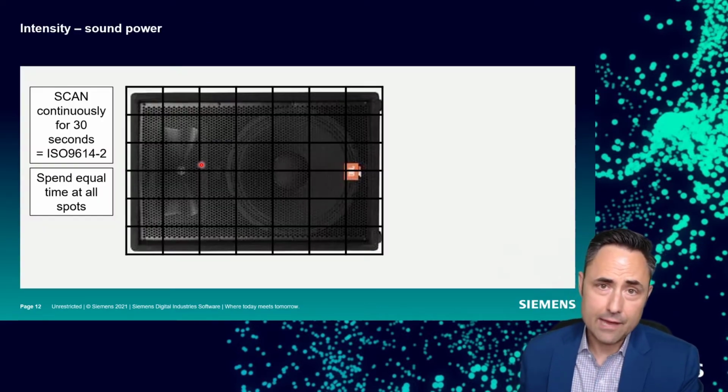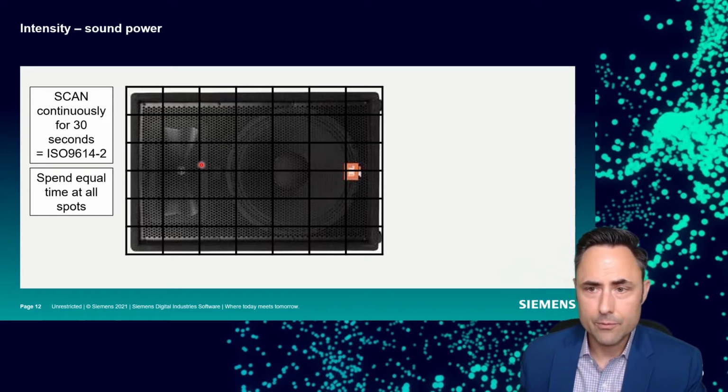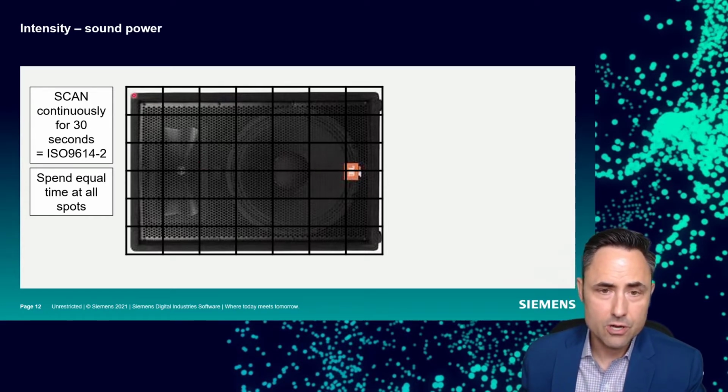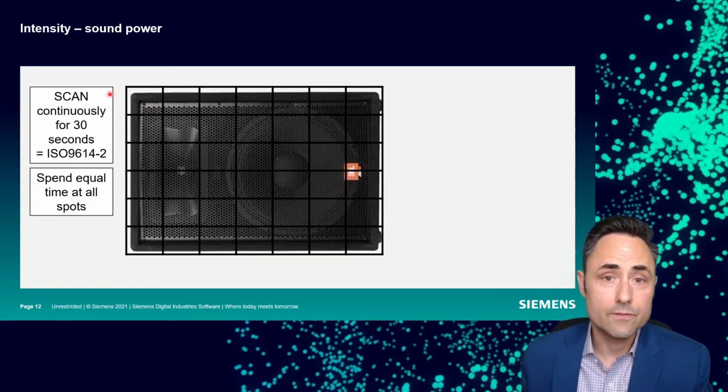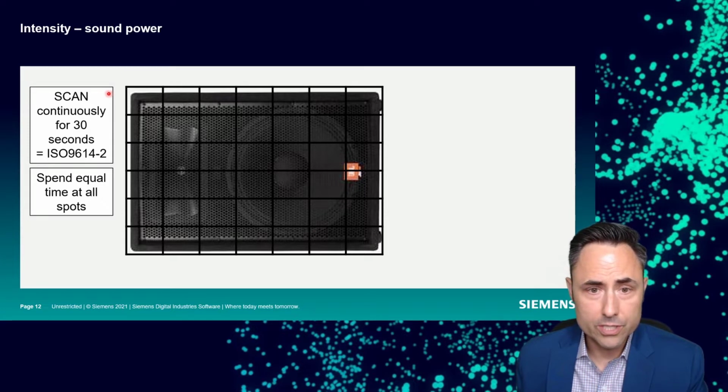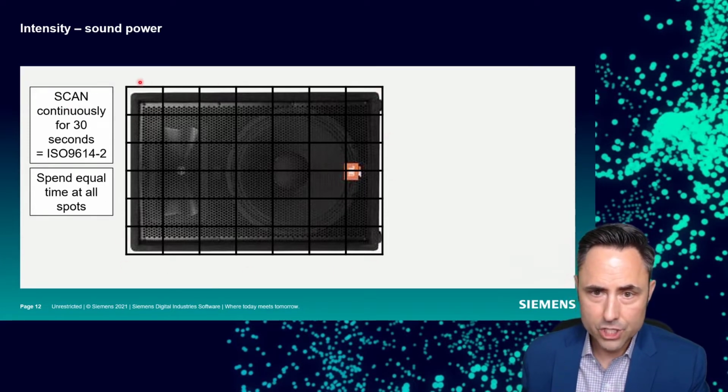So let's say we have our speaker here that we saw in our post-apocalyptic wasteland, and we're going to do some intensity measurements. And so we think, well, let's just do the scanning method because all I really care about is that sound power value, right? So we're going to scan continuously over our wire mesh test area.